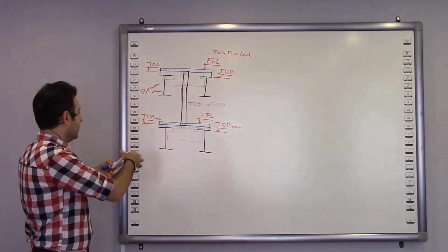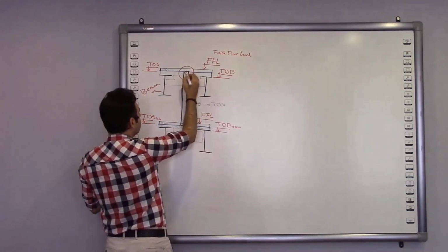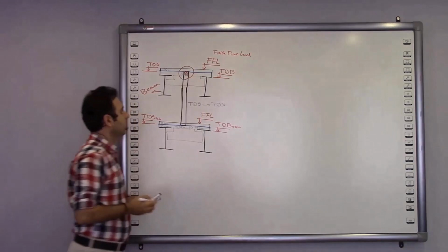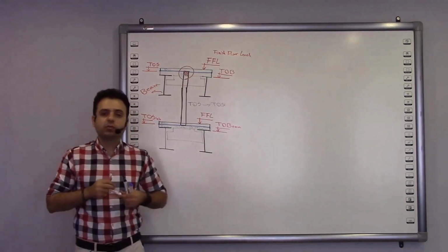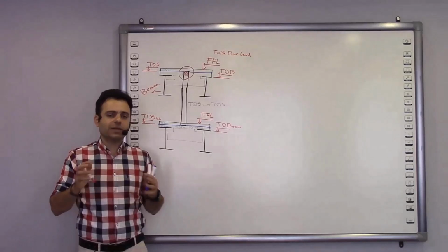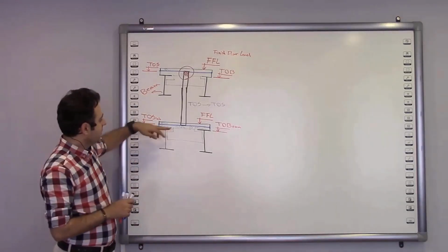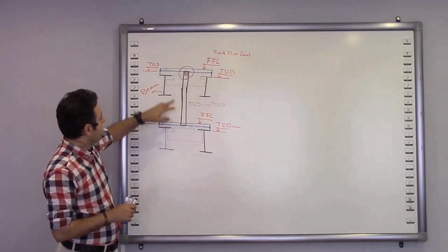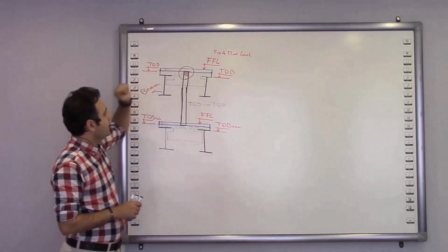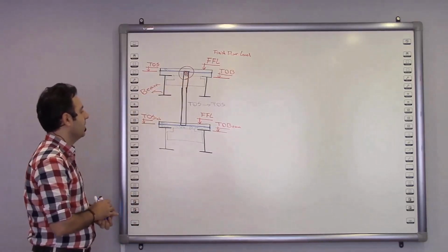Now, what happens here? Well, we have an interference here. See, the wall and the slab. This is the subject of our lesson in the next episode, and I will talk about it a lot in the next session. Right now, forget about it and draw your walls until the slab of the next floor, and I will talk about this interference next session.